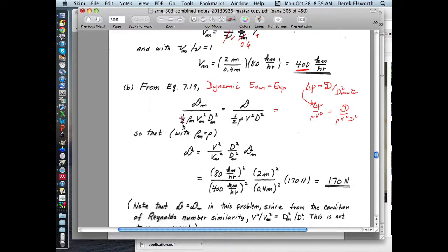You don't need the half on either side. Half just comes in as convention because it's a half v squared in Bernoulli, but you don't need the half. Now the question is, you want to know what's the force applied on your pole as a result of the wind? You measure this in the wind tunnel. The densities of the fluids are the same, so you don't care about those. They'll cross out. You know that you're doing it at 2 different velocities, which we've just said, in the wind tunnel. And you know that the diameters of your model and your real conditions scaled.